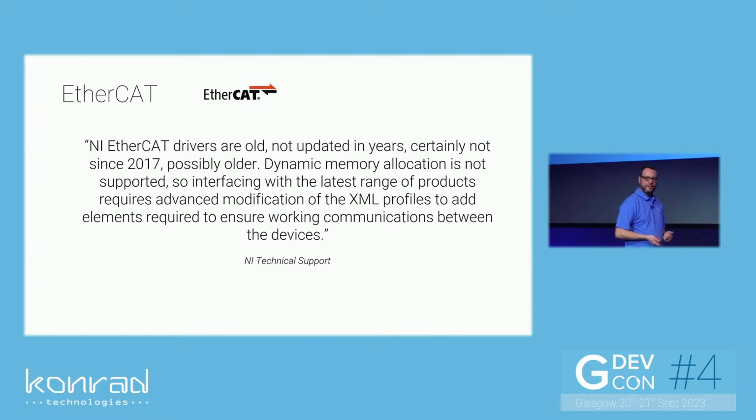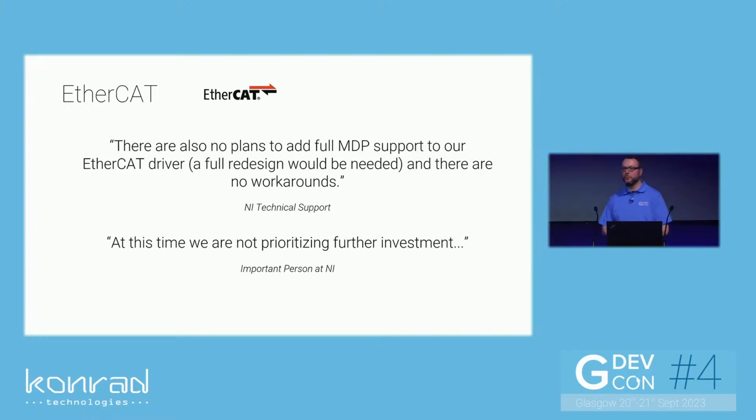This is because NI's EtherCAT drivers are old. They haven't been updated in years. Now, these are NI's words, by the way. Certainly not since 2017, possibly older. Dynamic memory allocation is not supported, so interfacing with the latest range of products requires advanced modification of the XML profiles, those ESI files, to add elements required to ensure working communication. There are no plans to add full modular device profile support to our driver. A full redesign would be needed, and there are no workarounds. At this time, we are not prioritizing further investment.